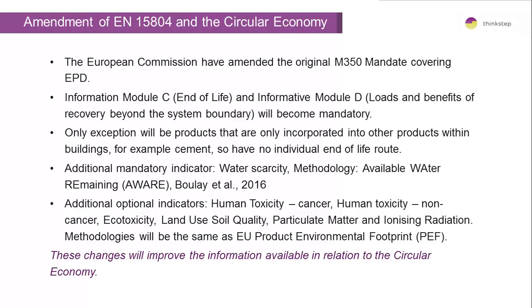There's work ongoing in terms of the European standards for environmental product declarations, and this arises from PEF, but that also has a circular approach. So they've asked us to look at this, and as part of that, there will be a mandatory provision of end-of-life data for all products. The only exceptions will be something like cement, which effectively doesn't come out of a building as itself, it comes out as concrete. So a concrete product will have to provide an end of life and information about any benefits from that recycling. And that's the same across all construction products.